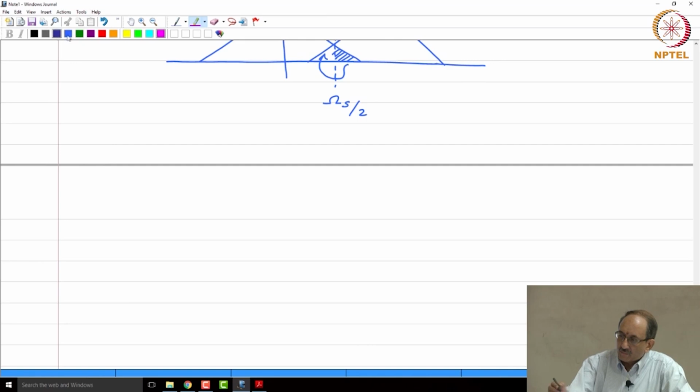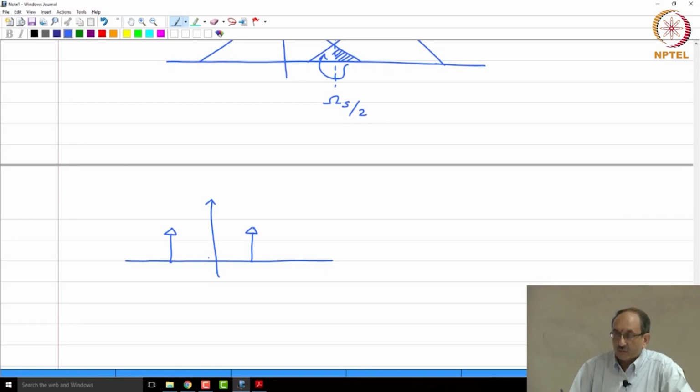So, this aliasing, which is really a higher frequency component appearing as if it is a lower frequency component because of undersampling, can easily be illustrated when you consider a sinusoid. So, let us consider a pure infinite duration sinusoid. Therefore, its frequency transform is 2 impulses. So, I am assuming that f naught is 8 kilohertz. So, this is the frequency of the sinusoid.